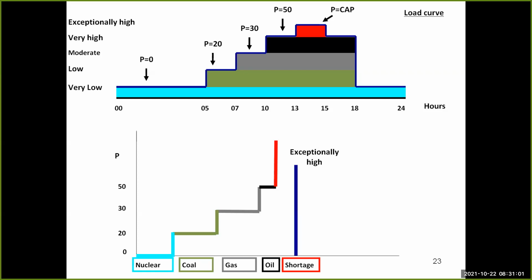Of course, when we add renewables to it, we add some extra complexity. But usually this variability of renewables is then added to the demand. That's actually the way to address this. So if you have renewables, you do not look at the gross demand, but you look at the net demand: demand minus what is produced by renewables. So this framework is still relevant and important today.